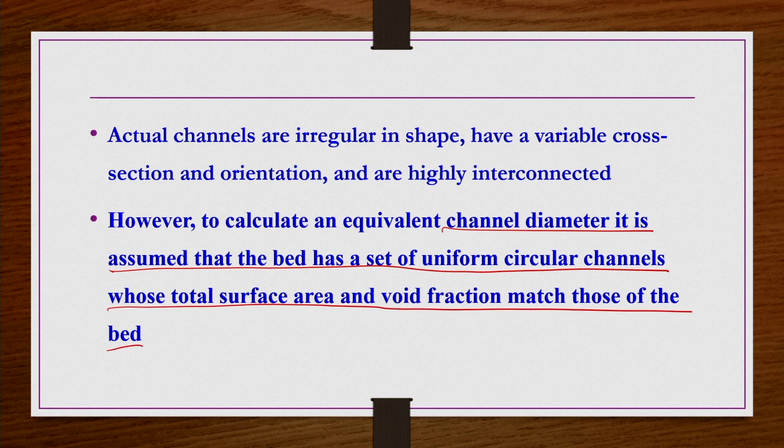Now, why are we doing this flow through packed beds in general? Though we have seen there are catalytic reactions, there is heat recovery, there is mass transfer in something like drying, etc. So then what is the point? Why are we using a packed bed? Why not do it in a single column or individual columns? That is because when we have this packing, the surface to volume ratio for a given packing dimension increases. It is very much higher compared to the single columns.